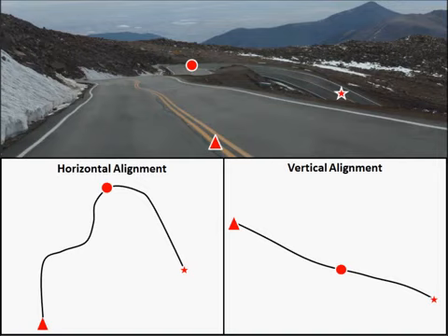Similar to the previous example, this example shows the same three perspectives. We see an example of a roadway with very complex horizontal alignment, but relatively simple alignment in the vertical plane. A driver on this section of roadway will travel downhill at a relatively constant grade in the vertical perspective, while experiencing a series of horizontal curves which will require significant left and right steering to remain on the roadway.